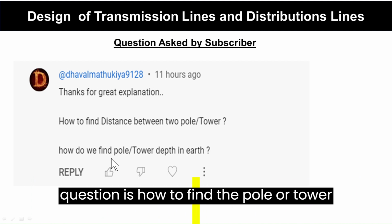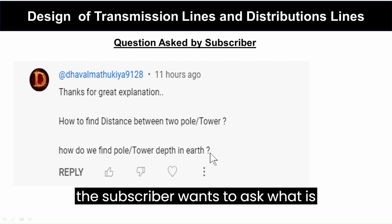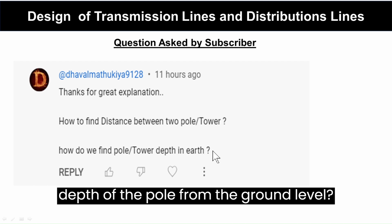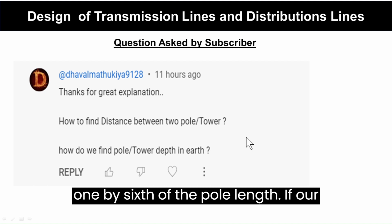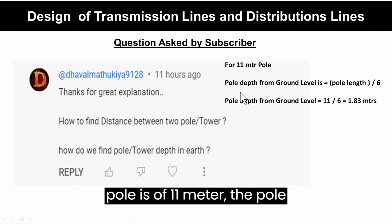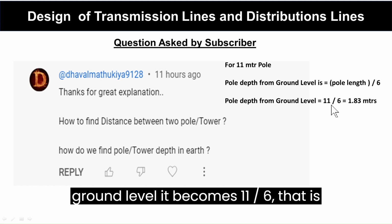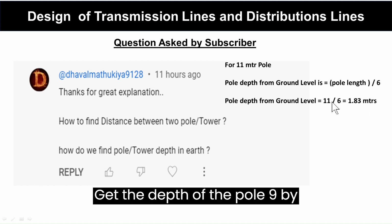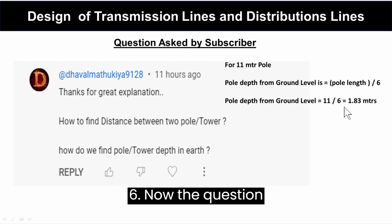The second question is how to find the pole or tower depth in earth. I think the subscriber wants to ask what should be the depth of the pole from the ground level. Generally, the depth of the pole is taken as 1/6 of the pole length. If our pole is of 11 meter, the pole depth from ground level is pole length divided by 6, that is 11 divided by 6, which is 1.8 meters. Similarly, if our pole is of 9 meter, we can get the depth of the pole as 9/6. Similarly, if our pole is of 13 meter, then 13/6.